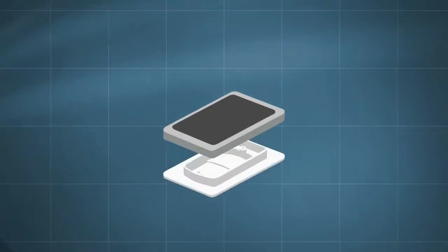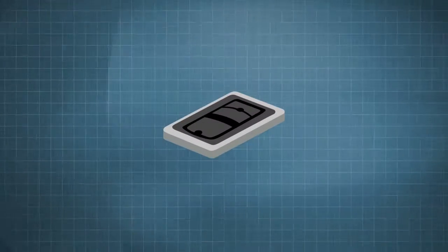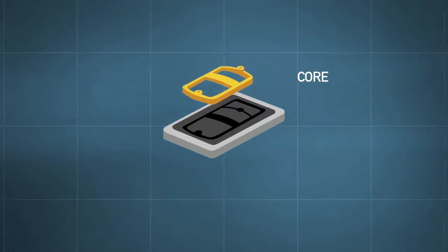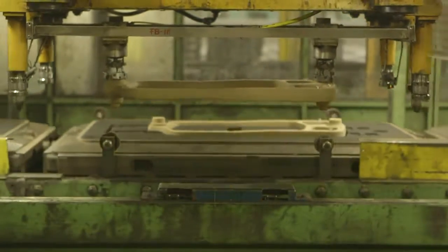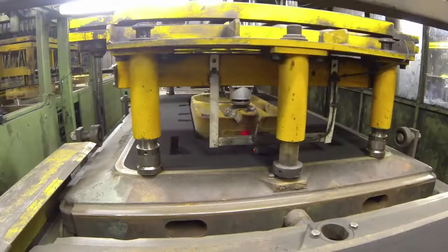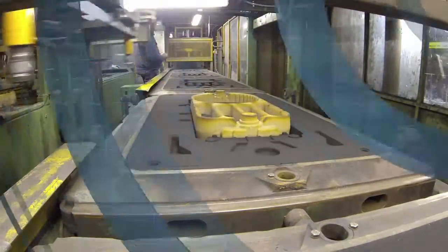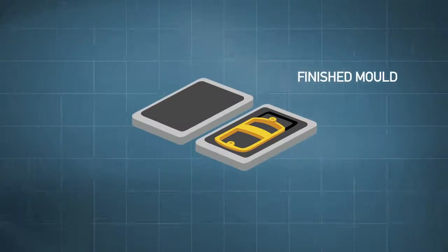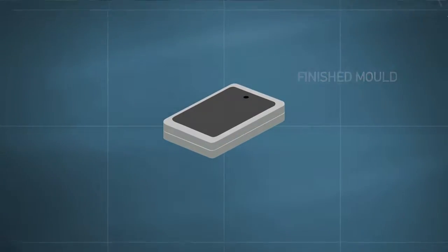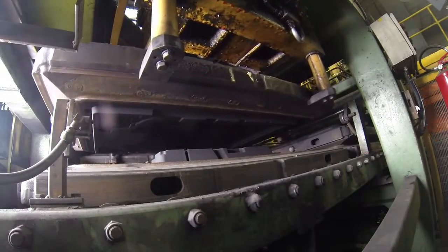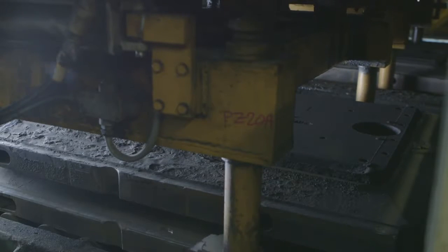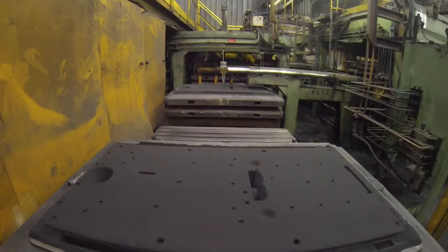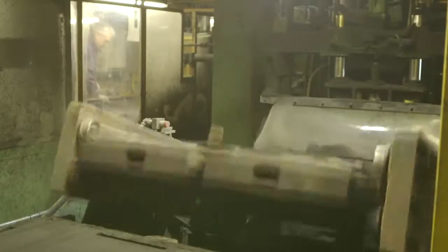If hollow products are made with the mold, the core must be placed inside, reproducing the empty part inside the finished iron casting. To close and complete the mold, the pattern is pressed into the sand by a second flask, which is then placed on top of the first one. The pouring gate is set up inside the second flask so that the molten cast iron can flow into the mold.